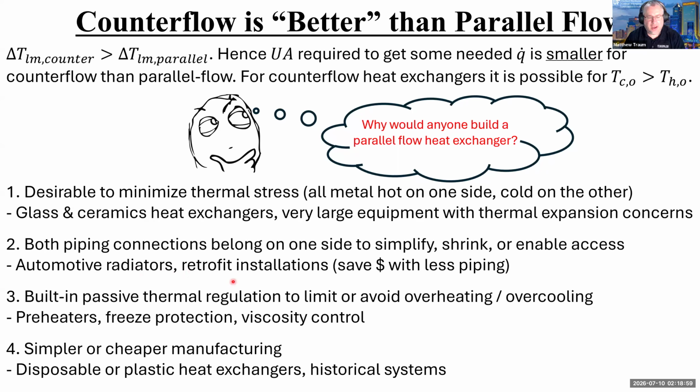So that's a reason. You also see this a lot with building retrofit installations. If somebody's adding a new hydronic system to a building, it actually saves money in the long run to run all the pipes to one place instead of running one big long pipe to the other end of the heat exchanger. In the end, it's just easier and cheaper to save money by using less piping. And so a lot of times people will retrofit with heat exchangers that are parallel flow rather than counterflow, so they can bring all the fittings into the same spot, right?